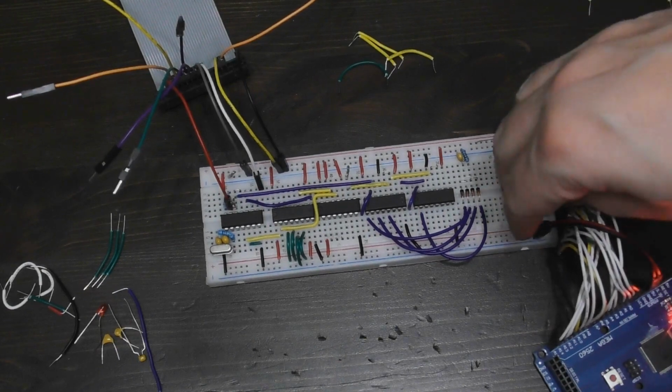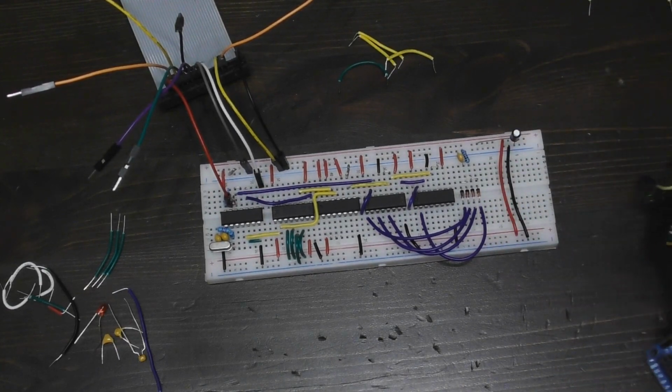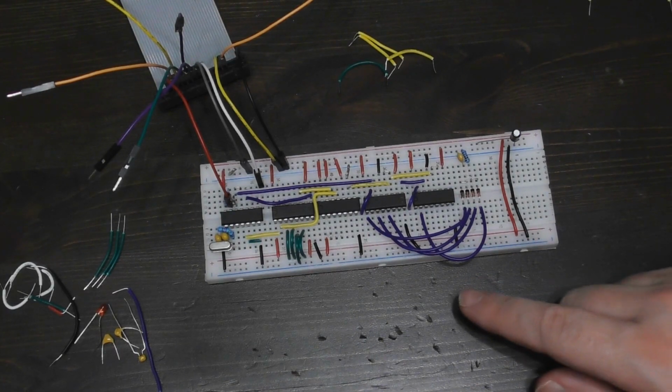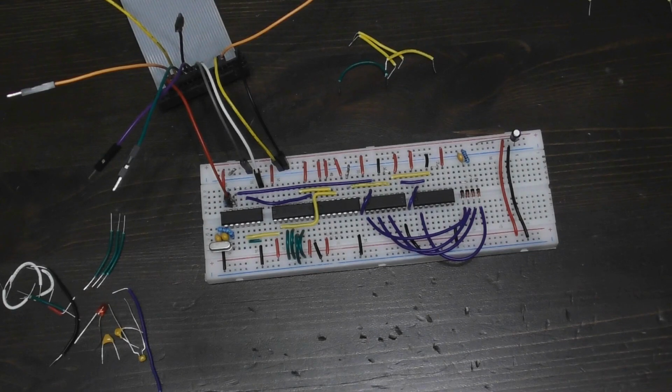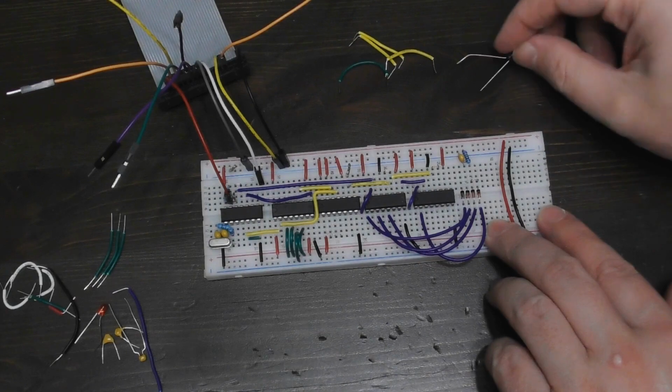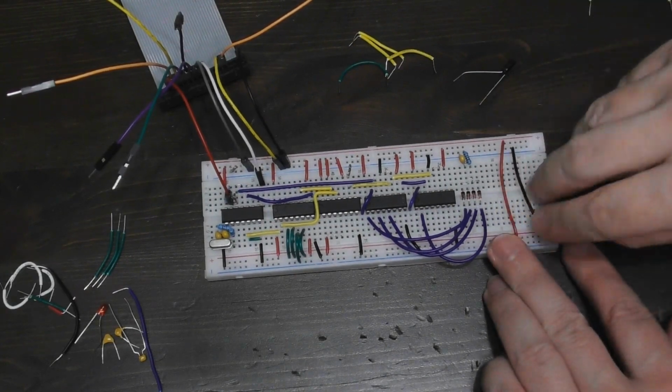So what I'm going to do next, if I just disconnect the Arduino power from the board, as I said towards the start of the video, is extend this to consistently advertise to the CPU or the Arduino or whatever is connected every time it thinks a byte has been received on the shift registers. And the way I'm going to do that is simply by using the address mark detection there to start a counter.